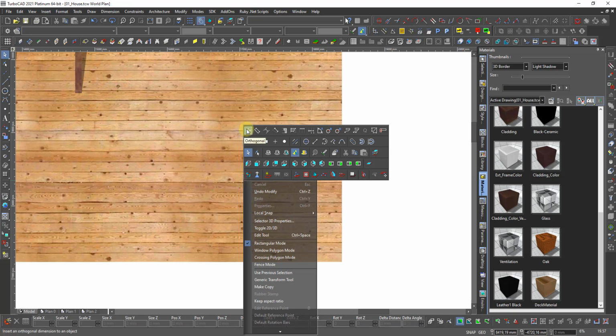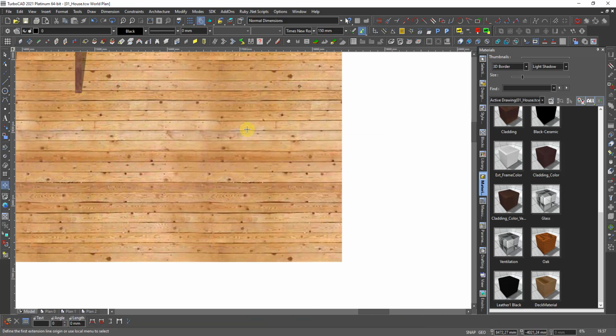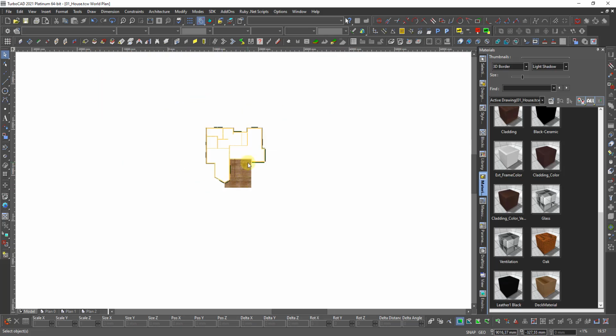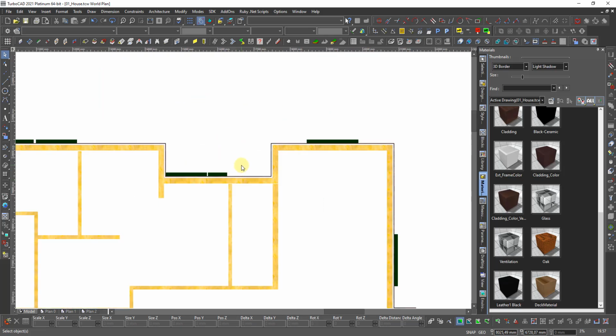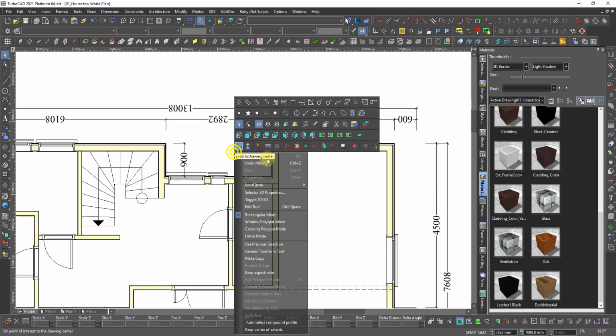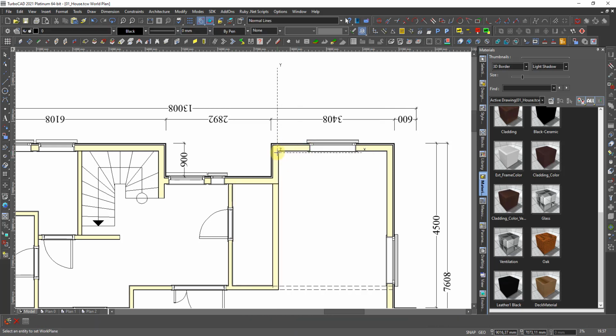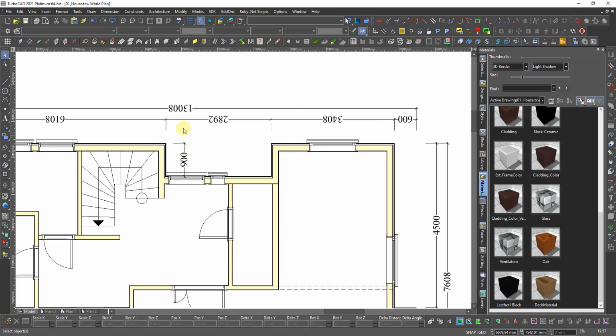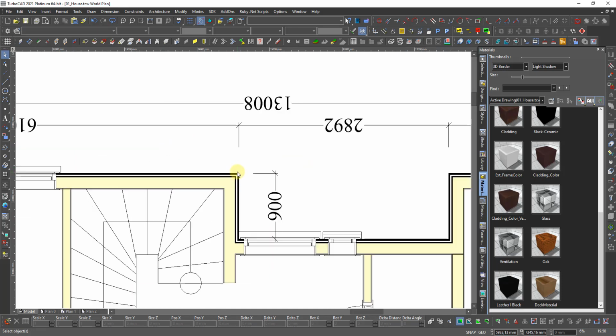Then I can take measurement from about there to there. That's 142, but I go a little bit down, so it's okay. Then we have this, and we should make a stair over here. So I go back to wireframe. I still have plane by entity on the wall. We want the stair to go 30 centimeters outside here.